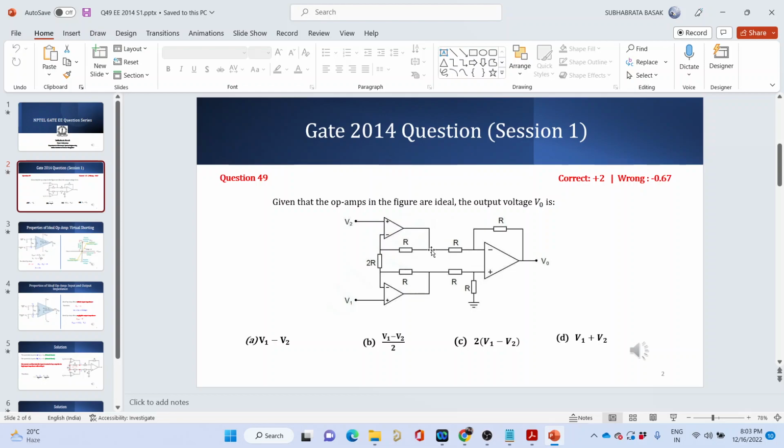So when this resistance is in kilo ohms, that is much lower than the mega ohm resistance, the imaginary resistance that exists between these two terminals. So we can assume that no current is flowing through this. If you attach a resistance of mega ohms or so, then you cannot neglect the input bias current which is flowing into the device. In such a case, you also cannot make this assumption.